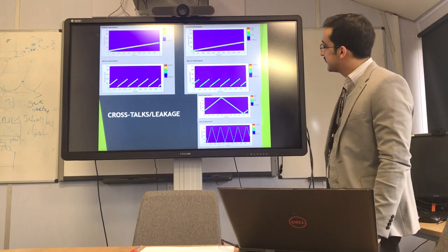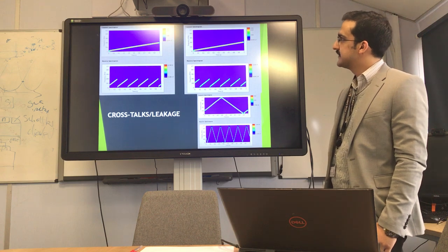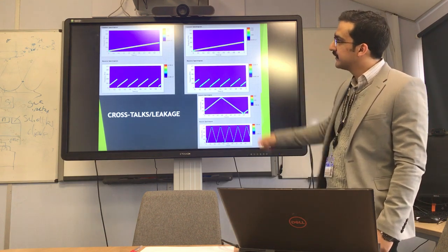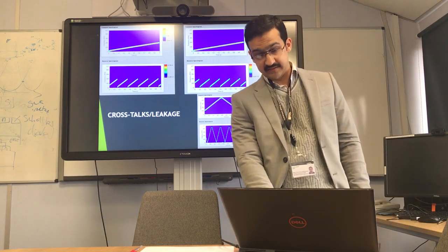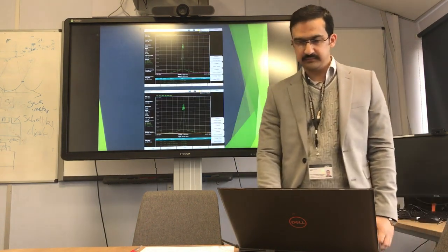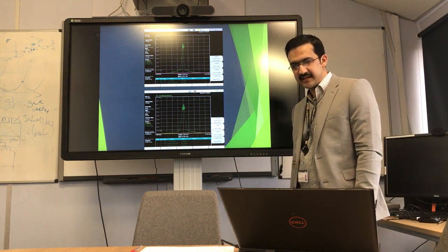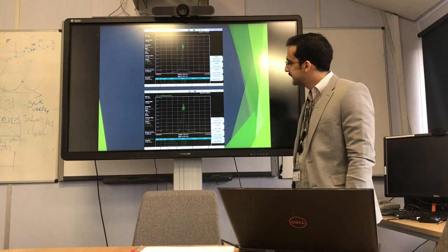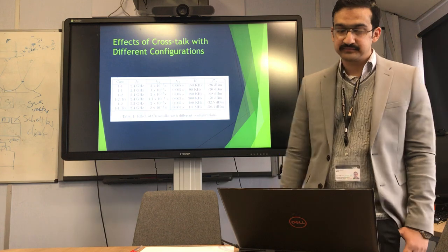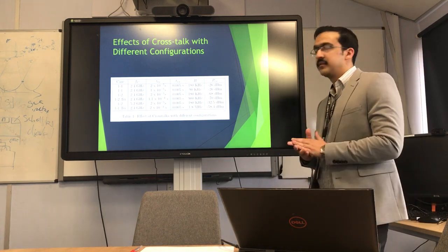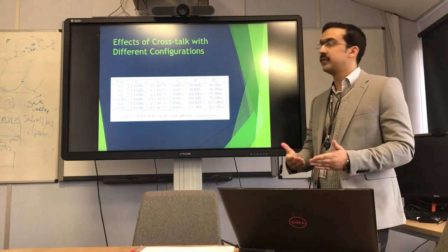The simulation that you're looking at on your screen shows the transmit spectrograms and the corresponding leakages that you observe on the receiver spectrogram. Different leakage issues were also seen using spectrum analyzers, and the results were recorded, because we wanted to see if a USRP is good enough for an FMCW implementation or not.